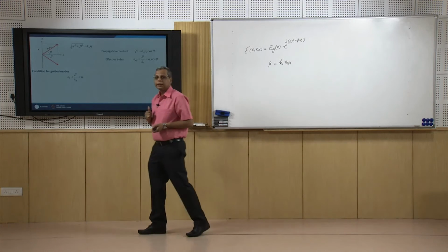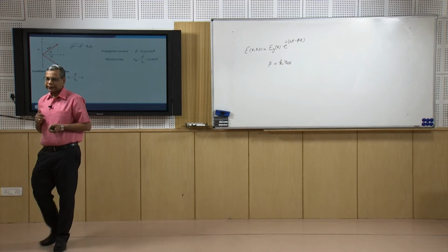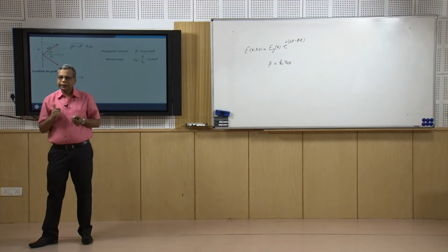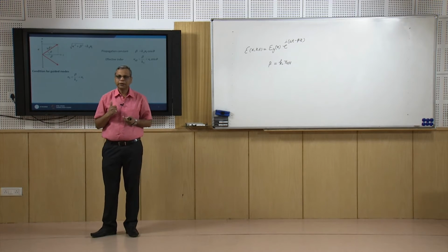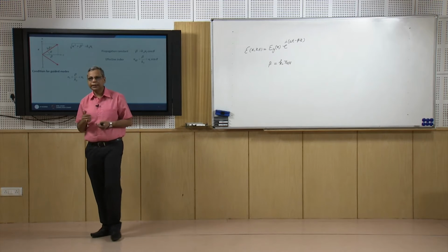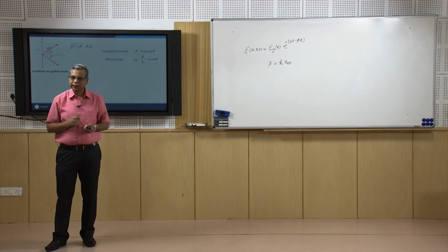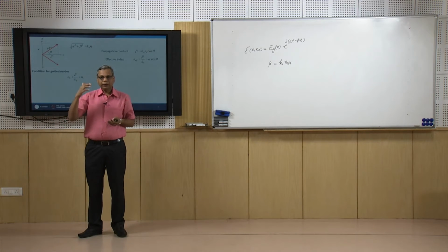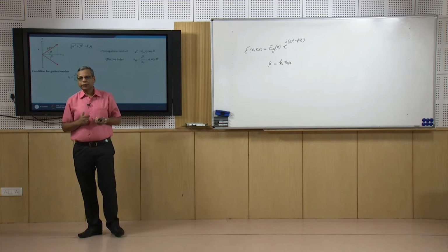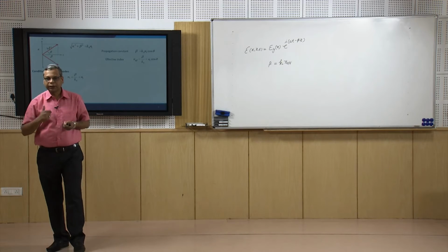If you remember, in one of the previous lectures I had said that intuitively I can understand the effective index of the mode as the effective refractive index felt by a particular field distribution, because the field is now distributed in the n1 and n2 regions. So, the effective refractive index would be somewhere between n2 and n1.